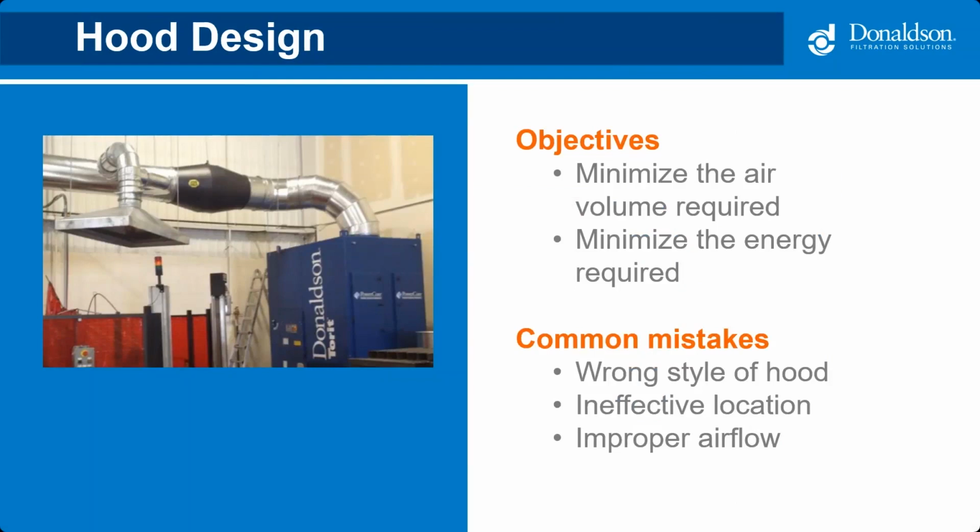When it comes to assessing an existing system, a few common mistakes that I see are the wrong style hoods being used. Maybe the hood is not located in an effective position, or we have inadequate airflow at that hood.